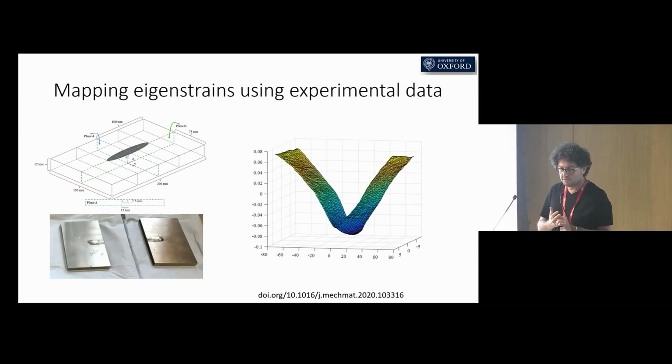So in a case study, I will show how we do it. Here we have a finite length weld. It is divided into half by non-contact cutting. How does it happen? It happens by the EDM cutting technique, and we do this cutting from plane A.